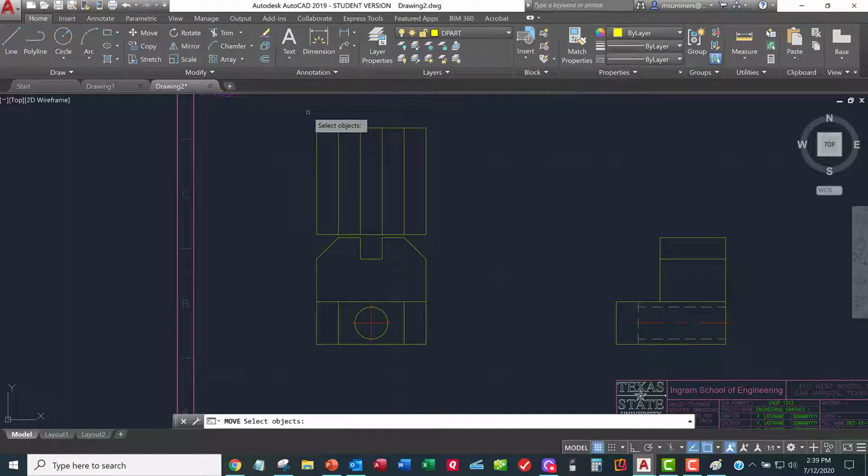If you click and let go and then click, you'll get a box and you'll get all of them. If you don't enclose all of them, you'll just get the ones that are completely enclosed. Here, all I'm going to get is that top line. If I come down here, I want to get all of those guys. Okay? Another option is to click. So that's top left, click and let go. Bottom right, click. You'll get that way. But they all have to be inside the box.